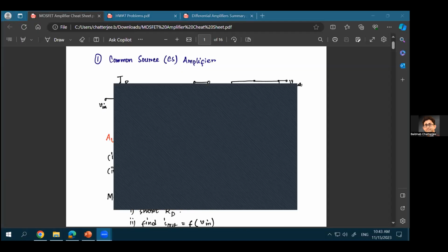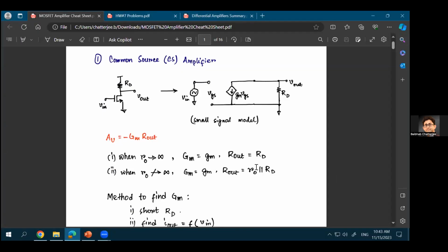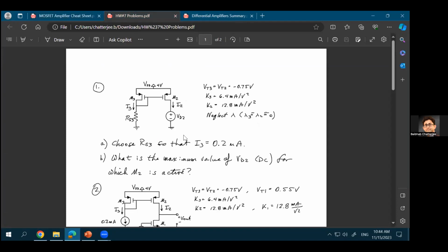Yeah. So, I understand there are multiple questions on homework 7 as well, particularly because it sometimes deals with PMOS transistors, and some of you might have a little bit of confusion on PMOS transistors. But then again, the best way to deal with PMOS transistors is that you use the same equation as your NMOS transistor, but remember that the drain becomes source for a PMOS transistor.